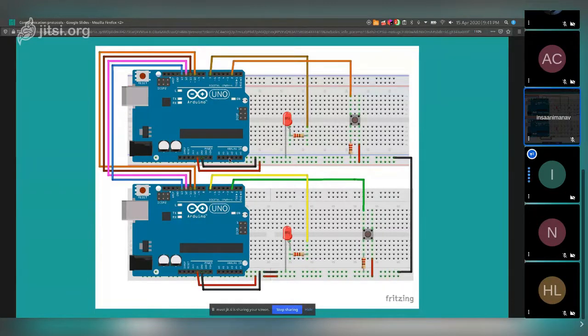I have 2 ways for doing that. The first one is to continuously check whether button 1 is pressed, 2 is pressed, or 3 is pressed, then loop again to check that. But sometimes we might miss the button being pressed. So let's say before the controller checks button 2, I press it and the controller misses it. So the input's gone, which is kind of a problem.